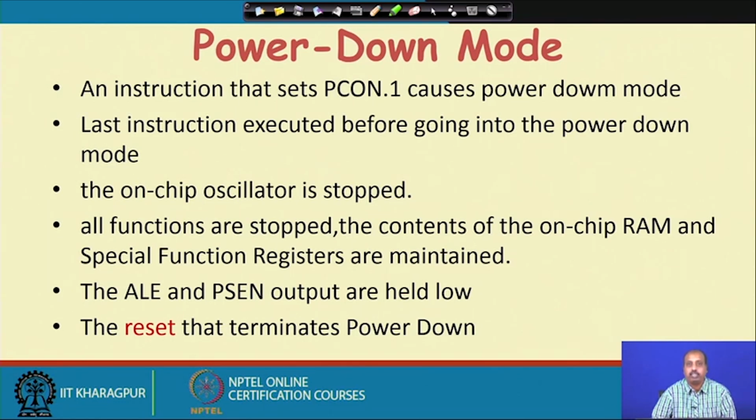So, unlike idle mode, where interrupts can turn off the idle mode, in case of power down mode only the reset operation can end this power down mode and take the processor out of it. These are very useful when we are talking about this power handling part. They are very much useful for